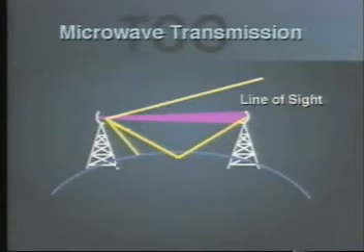Also, the curvature of the Earth. As you get 20 or 30 or 40 miles apart, the curvature of the Earth starts to play a role in it, so we keep these towers and antennas about 20 to 25 miles apart. So we can transmit tremendous amounts of data because microwave works like radio. We can project a lot of information in a straight line between two antennas miles and miles apart. But that's sometimes difficult to visualize. Let's take another trip down to the laboratory where I'll try and do another little demonstration to give you an idea how microwave works.